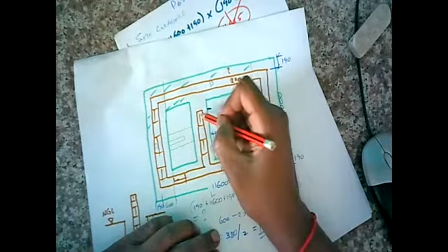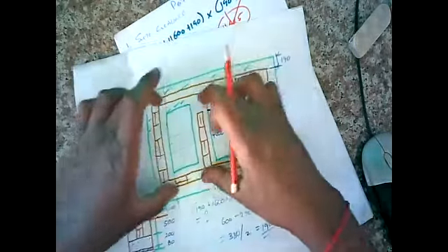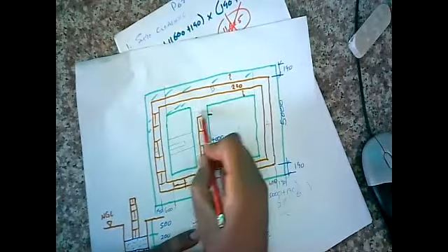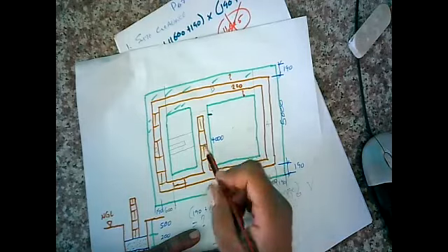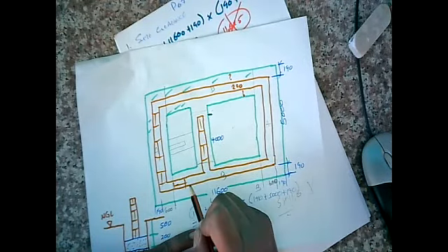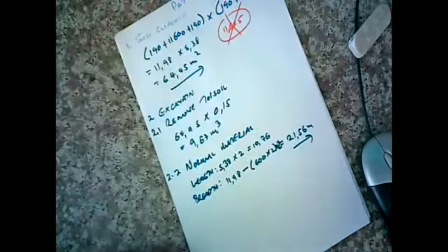But when we come to brickwork, it stops there. Just brickwork. Foundation all the way to the other end. You basically close the square or the rectangle. There's no cavity here that allows, if there's movement, for this to break away. That's basically one of the reasons for closing it up.